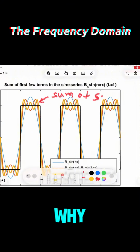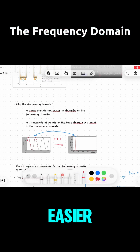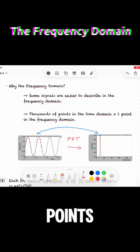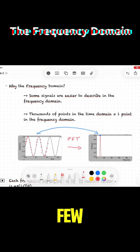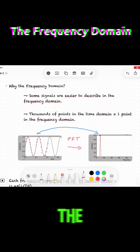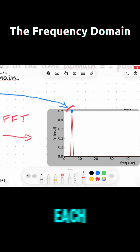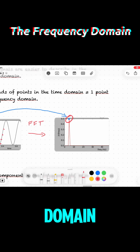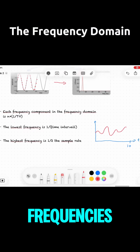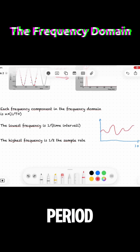This leads to the question, why use the frequency domain at all? Some signals are simply much easier to describe this way. Instead of dealing with thousands of time domain points, we can describe a signal with a few frequency components and their amplitudes. In some cases, thousands of points in the time domain collapse down to a single point in the frequency domain. Each frequency component appears at multiples of the fundamental frequency. In other words, the frequencies are at n times 1 over t0, where t0 is the period of the signal.